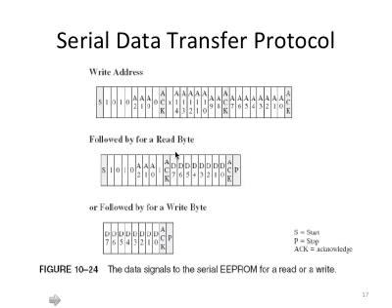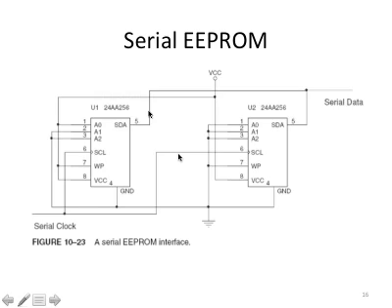And then this A2, A1, A0 is the value of the address pins. For our case, if those 3 bits are 0, 0, 0, that is to say, I want to access the chip on the right. Why? Because that's how we identify this chip. If those 3 bits are 0, 0, 1, that's to say, I want to access the chip on the left.